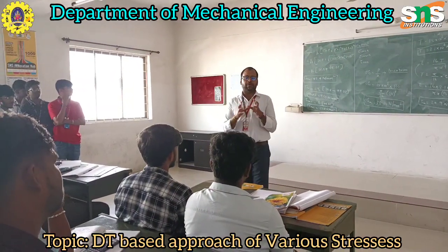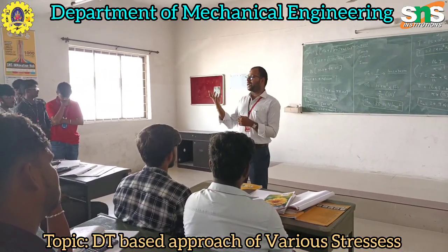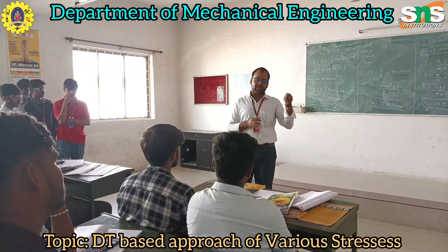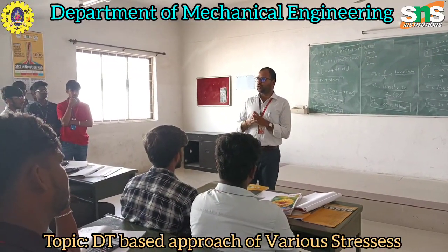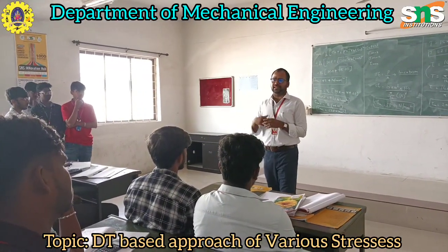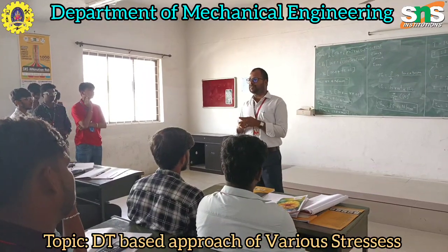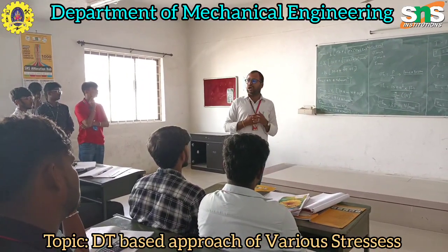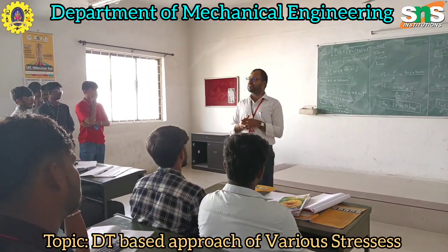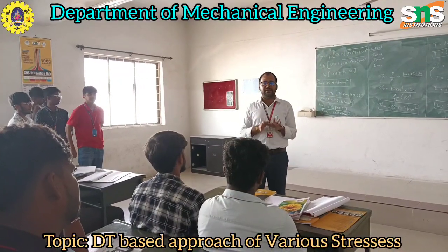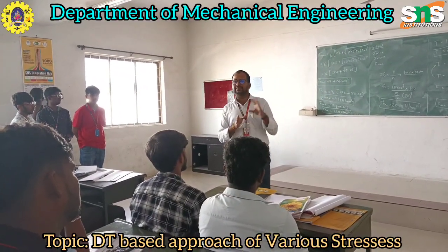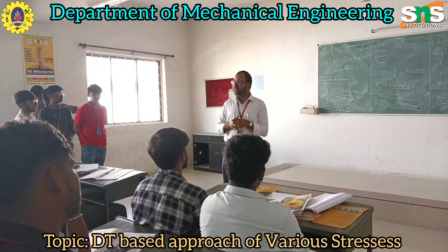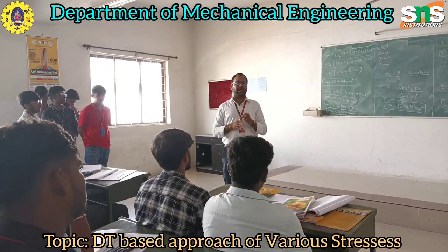With the help of the image you can understand the concept. This problem comes under principal stress. Palak already told the three formulas. Instead of the three formulas, we can calculate the torque with the help of the torsion equation, T equals pi by 16 into tau into d cube. With this relationship we can find the maximum shear, which is called tau.